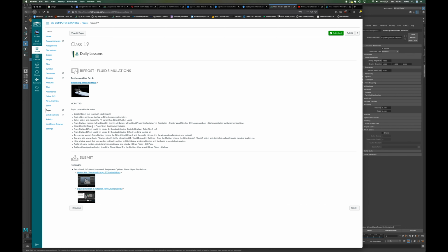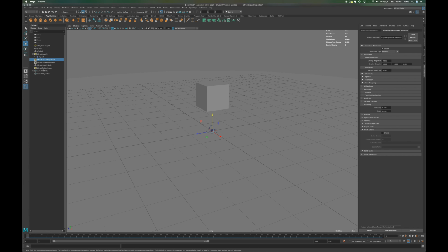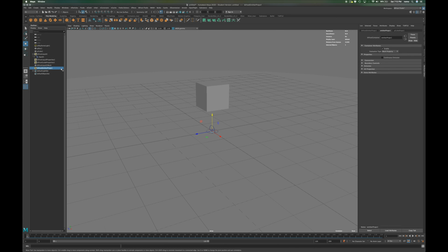Then we're going to go to the Bifrost Emitter Props 1 and the properties and do continuous emission. So down here a little bit in my outliner, you see Bifrost Emitter Props 1. And right here under properties, we want to turn on continuous emissions. That alone, if I do that now we can see the blue dots, and when I hit play, there they are. They will continuously emit. In the past, Bifrost has sometimes had some problems where your emissions will disappear and then come back, and often that can be solved by just toggling the continuous emissions button on and off. So if that ever happens or something just disappears and it doesn't make sense, try coming back to the emitter props and click that on and off.